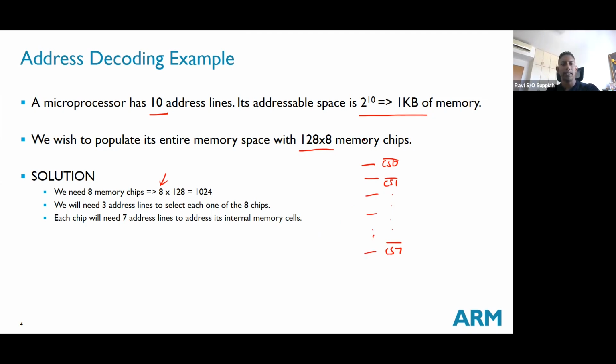One of the easiest ways to do it is if this number here, you can directly map it to a power of 2. In this case, we know that 2 power 3 equals 8, and we want 8 outputs and 3 inputs. Since to generate 8 outputs I need 3 inputs, I can use a 3 to 8 decoder.